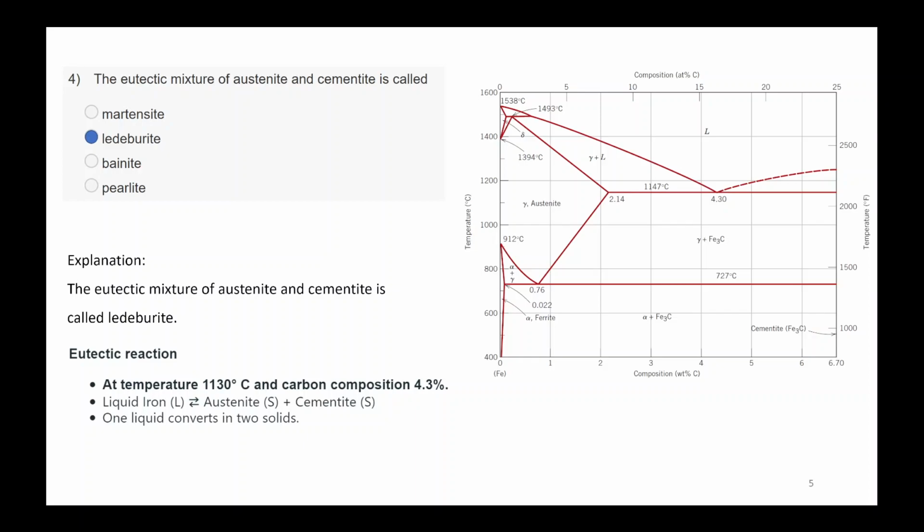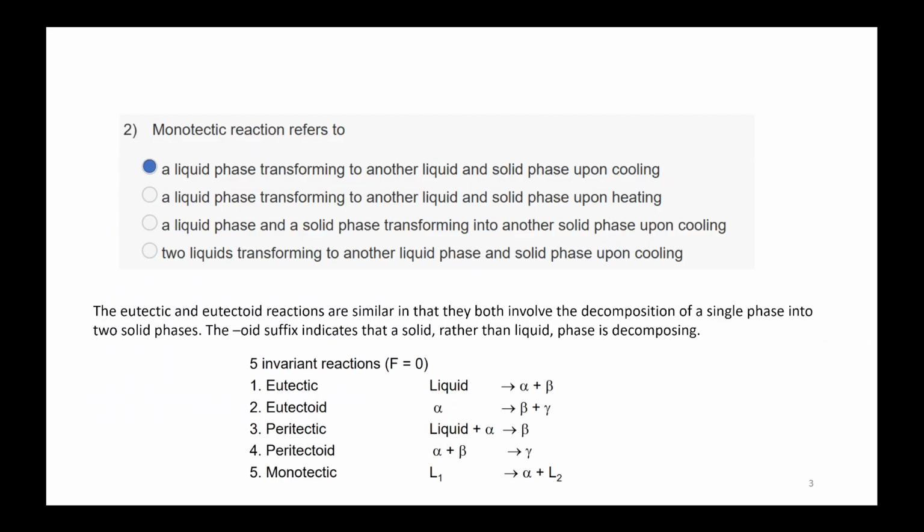So, by supercooled liquid, it's actually martensite. So it doesn't necessarily need to cross that C curve. Can you repeat? A supercooled liquid state. It can be martensite, and it can also be retained austenite, some percentage of retained austenite, so it might not change as well if your MS is not approached.